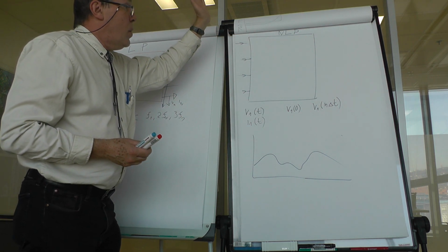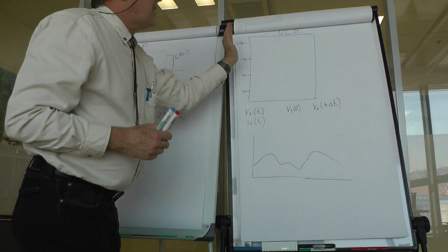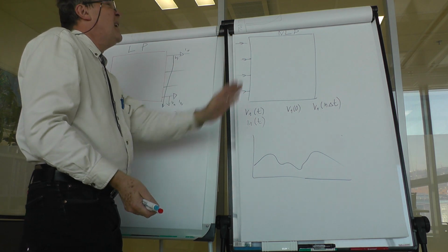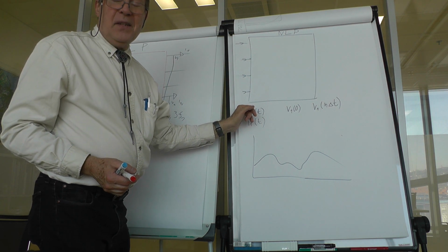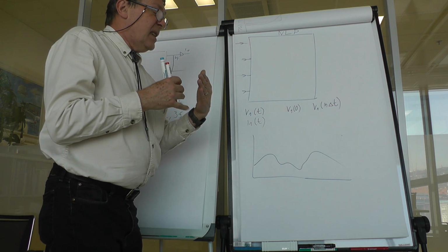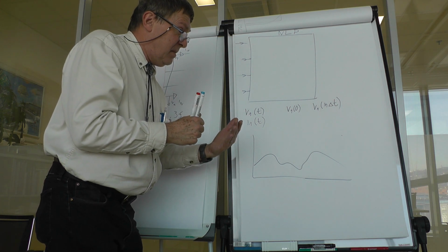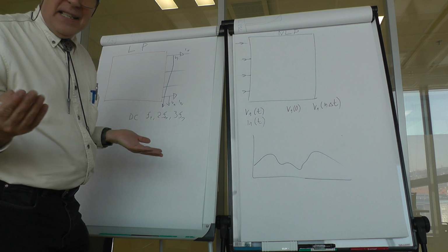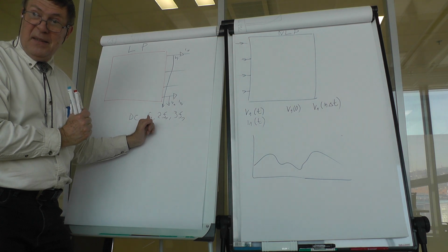That is, you test some input, run it through the chain, and get the same input after the process. And the process consists of time domain simulation of the nonlinear part. The time domain simulation must run at least as long as the initial transient effects are gone, and it must cover at least 1 full time period of the basic frequency component.